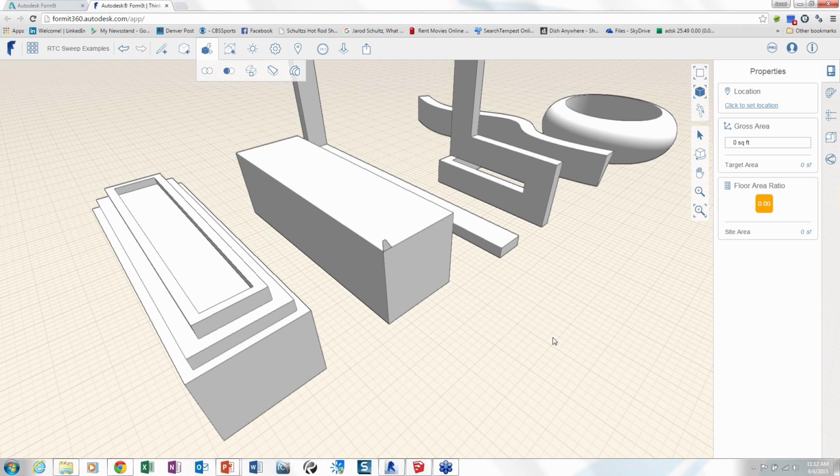Yeah, let me jump in here with some of the comments that we've gotten as you've been going along. One cool workflow that I hadn't heard of before was grabbing the Google image from either FormIt or from SketchUp, and then applying that in Revit as a material by face or something like that. Just because the Google image doesn't come across in the FormIt to Revit translation doesn't mean you can't still get an image into Revit. It only works in realistic mode, right? When you're doing realistic or rendering, because it's textured, but you can still get that terrain image over there. So that's a great suggestion.